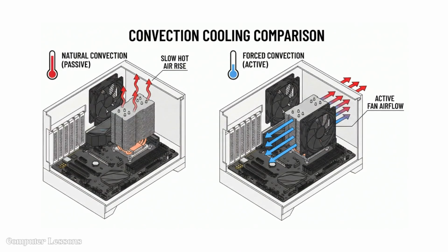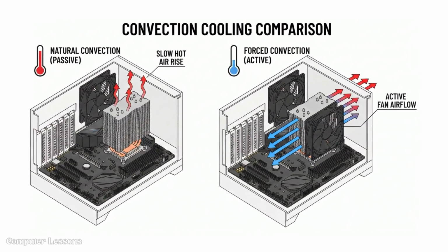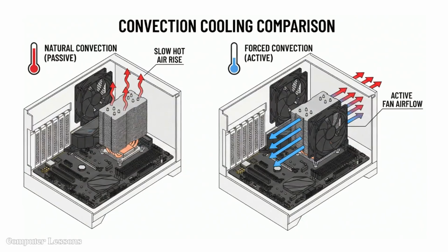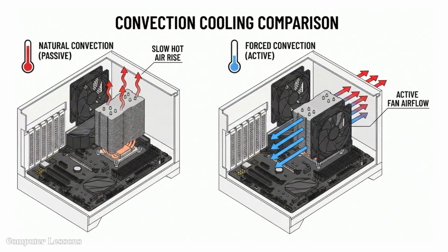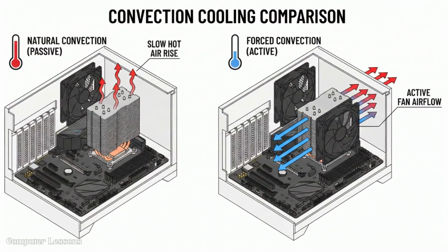Now that the heat is spread across the fins, we need to remove it from the case using convection. Natural convection, where hot air rises, is too slow for high-performance computing. We use forced convection by attaching fans.